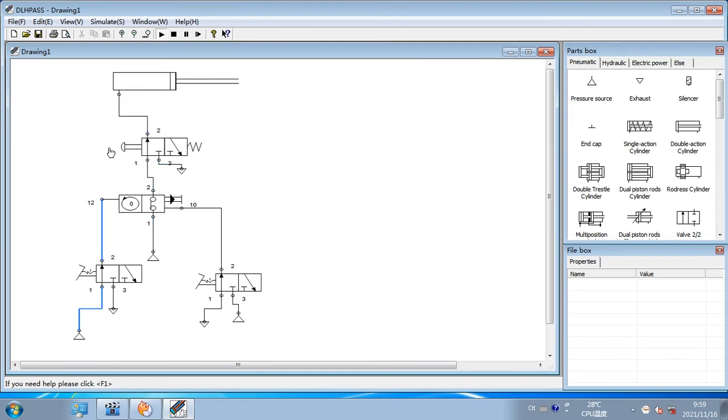The next you want to do is to press this. You can see it extends, and when you release, it retracts because it's a single acting cylinder which has a valve which has a spring in it. And then you release, and when you press this, you can see it resets. So you release this, you press this, it starts counting.